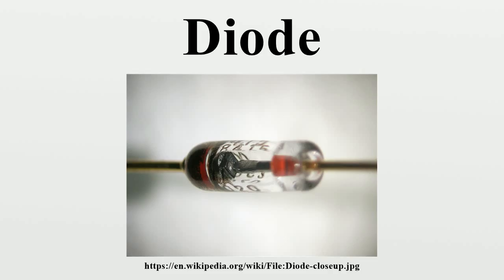The crystal detector in these early crystal radio sets consisted of an adjustable wire point contact, often made of gold or platinum due to their incorrodible nature, which could be manually moved over the face of the crystal in order to obtain a portion of that mineral with a crystal that provided the optimum signal.